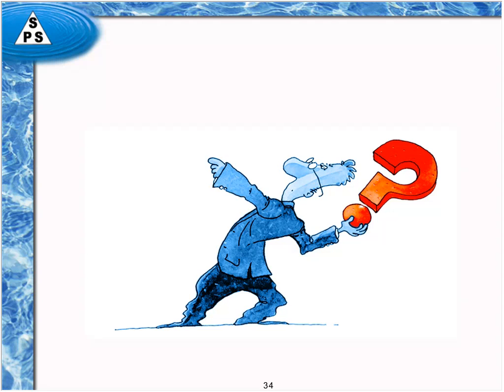Going down from that, peracetic acid and hydrogen peroxide alone, individually, were about neck and neck, even for second place. Third place would probably be something like hypochlorite. The problem with hypochlorite is that the alkaline pH that it typically exists at is where the hypochlorous acid molecule, which is the business end of the chlorine, is the least effective. And so if you were to acidify the hypochlorite treatment concentration that's in the hundreds of ppm level, it would be much more effective.